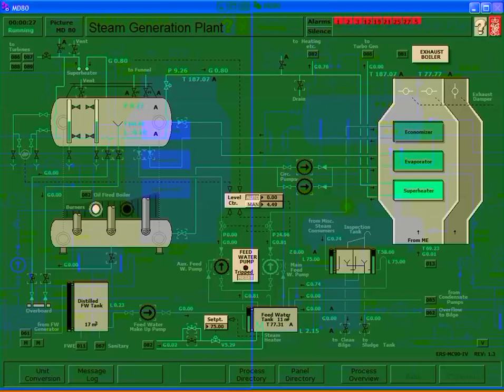In other words, we don't want the sulfur in the fuel to combine with the moisture present in the flue gas and condense out to sulfuric acid, because that sulfuric acid would very quickly eat up my economizer. So we have to heat this tank to make sure that the incoming water is hot enough to prevent that.